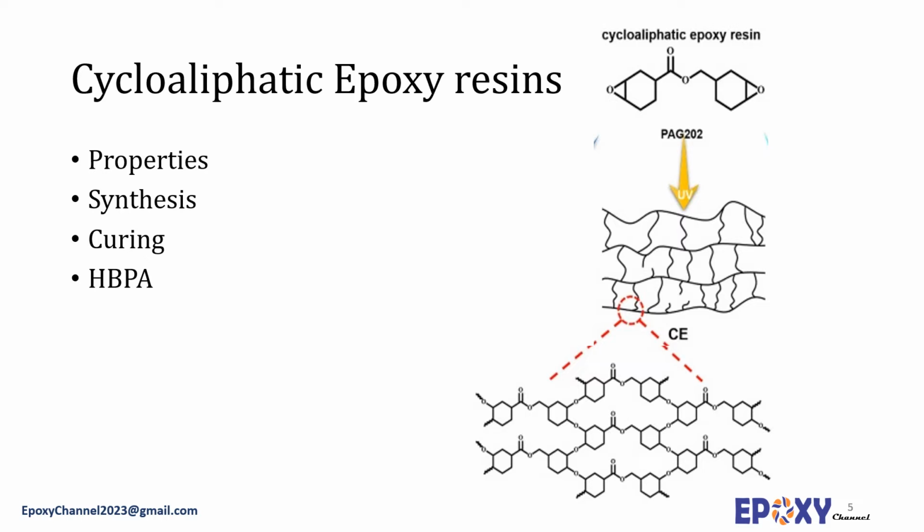Cycloaliphatic curing agents are generally more expensive than regular curing agents. Due to the low dielectric constant and the absence of chloride, cycloaliphatic epoxies are often used to encapsulate electronic systems such as microchips or LEDs. They are also used for radiation-cured paints and varnishes. Due to their high prices, however, they have so far been limited to such applications.